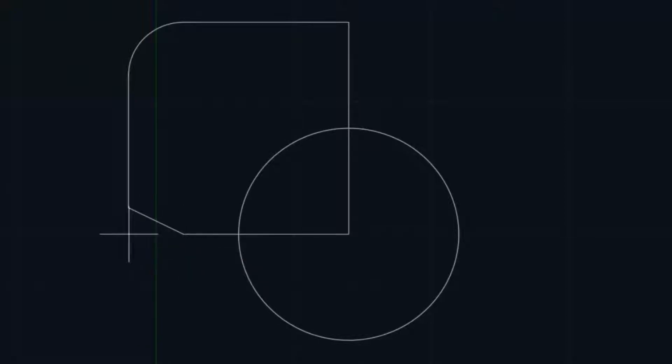So from that point there, I'm going to go 1 inch across. So it's 1 click, 2 clicks, and it's 1.5 inches up. So it's 1, 2, 3, and you can see I'm 1.5 inches up from that corner. So I click. That then puts the center of the circle down, and as they're 1 inch circles with a 1/2 inch rad, I just move across to the right, and you can see the polar is 1/2 inch on the rad. I left click directly in that position. It drops my circle where I need it.